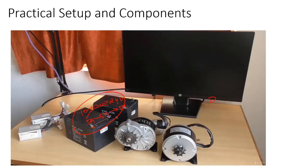So 24 volts into 5 amps, because power is voltage multiplied by current. So it is nothing but 5 4s are 20, 5 2s are 10, so 120 volt ampere. That is nothing but a 120 watts system. So the source is 120 watts. The motors should also be of 120 watts power. Otherwise, if they are not of that wattage, then we need to alter that using DC DC converters.